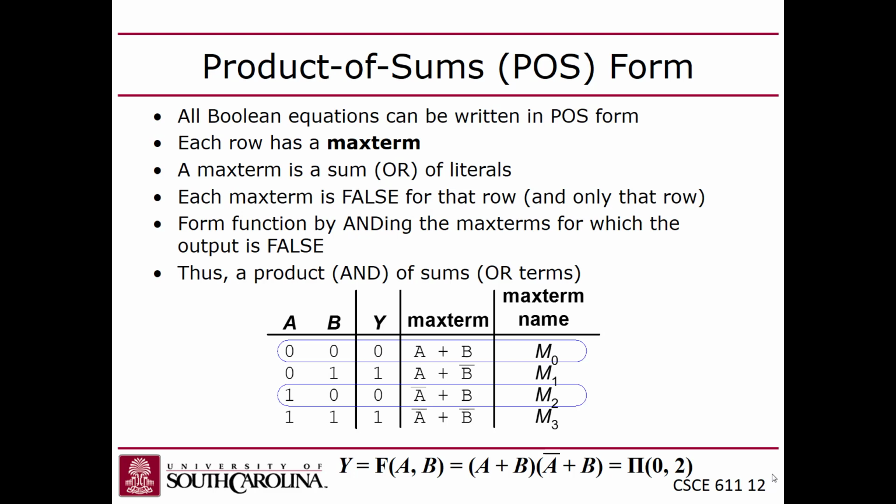actually what happens is that you start out with the top level or, right? That becomes an and, right? So you still end up with not A, not B, but that's negated, right? And then this becomes an and, right? And then this is A and not B negated, right? So that's the first De Morgan's law. And then you apply De Morgan's law to both sides.